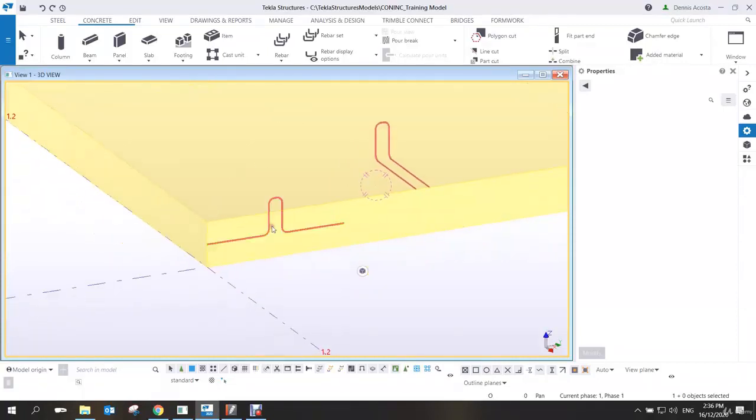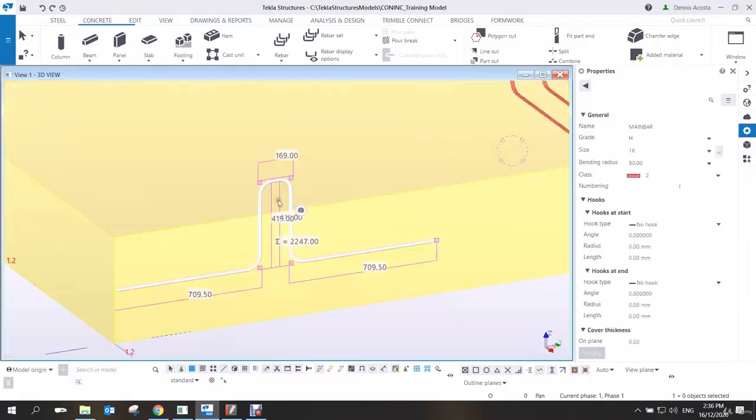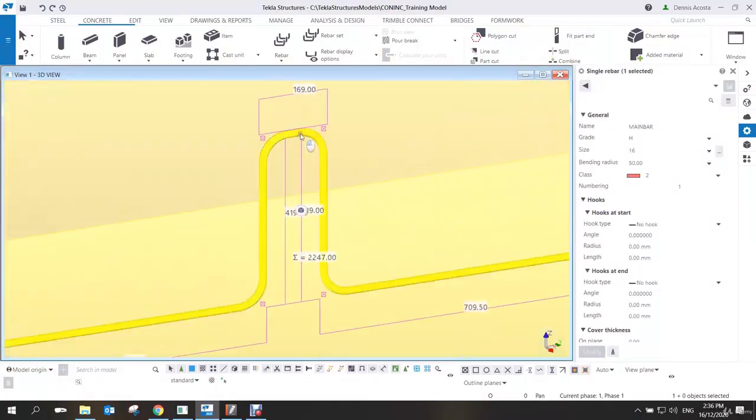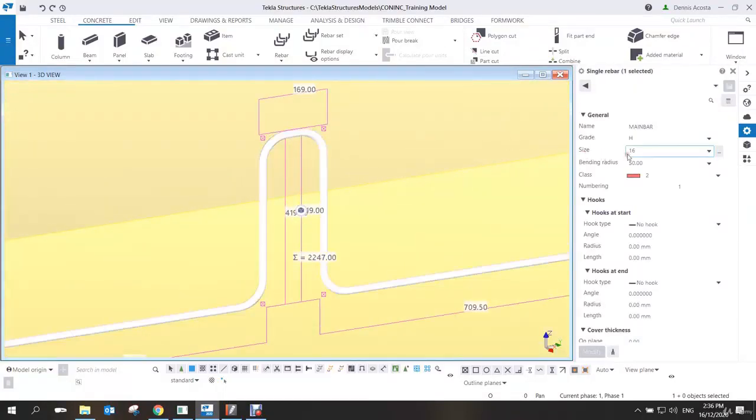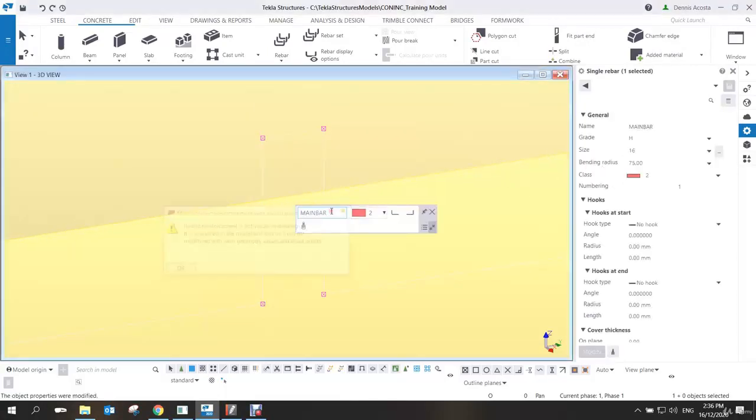So now you can put that one on the edge and then you can just move wherever you want to move. So in this case, now what if I want this one more rounding? Let's say if this one is 150, let's say 75. Look, 75 doesn't work because my spacing is 150 and then after the radius 75, it's more than 150. Okay?